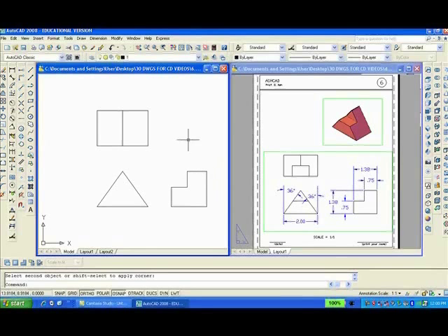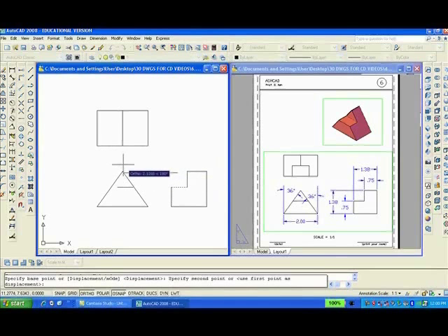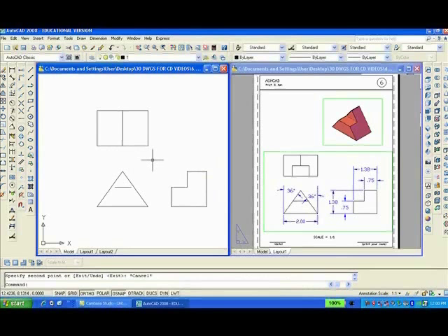And that view looks okay. Now I want to copy this line and bring it over here somewhere. And I can extend, EX, enter, extend to that line, enter that one, enter. So the front view and the right side view are okay, but the top view is still wrong. So I'm going to O, enter, 0.75, enter, bring that down.